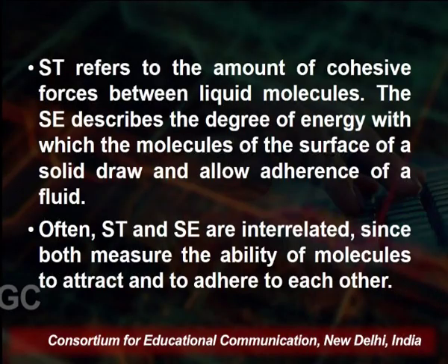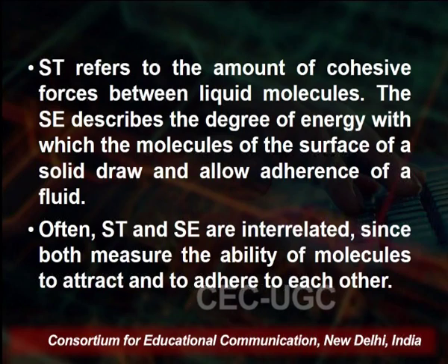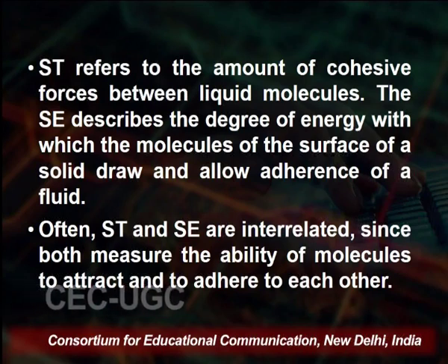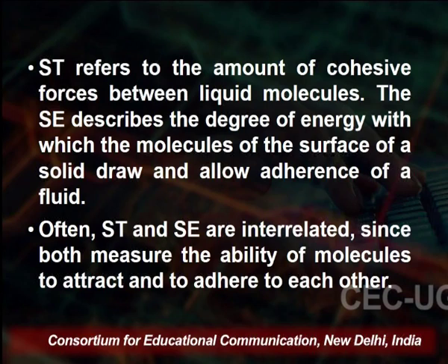This implies that the cohesive forces associated with the fluid are greater than the forces associated with the interaction of the fluid with the surface. So surface tension refers to the amount of cohesive forces between the fluid molecules. We describe surface energy as the degree of energy with which the molecules at the surface of a solid draw and allow adhesion of the fluid.